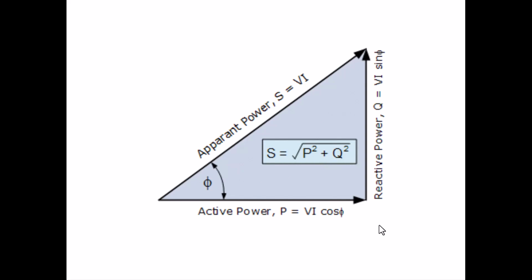Therefore, apparent power is a critical design parameter for power system infrastructure, as it determines the rating and sizing of electrical components in AC power networks. In summary, we can say that real power defines how much energy is used, apparent power defines how much capacity the equipment must handle. Power system components must be rated for apparent power to safely carry the total electrical load.